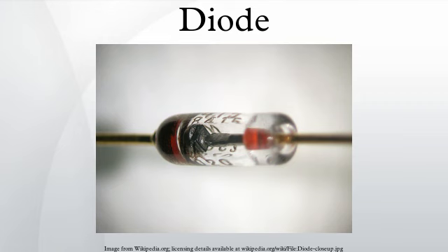Temperature measurements. A diode can be used as a temperature measuring device, since the forward voltage drop across the diode depends on temperature, as in a silicon bandgap temperature sensor. From the Shockley ideal diode equation given above, it might appear that the voltage has a positive temperature coefficient, but usually the variation of the reverse saturation current term is more significant than the variation in the thermal voltage term.